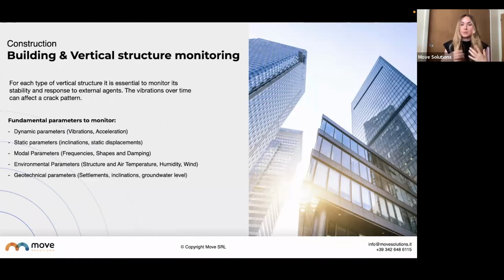So we can monitor them not just for vibrations, but we can also perform that modal analysis that I was talking about earlier that we can do on the bridges. We can perform the same modal analysis on a building. So you can see over time, something is starting to shift within that building and understand what's going on with it. So maybe it's an environmental factor, perhaps there was an earthquake, and then after the earthquake, you see that the building has shifted a bit and moved.